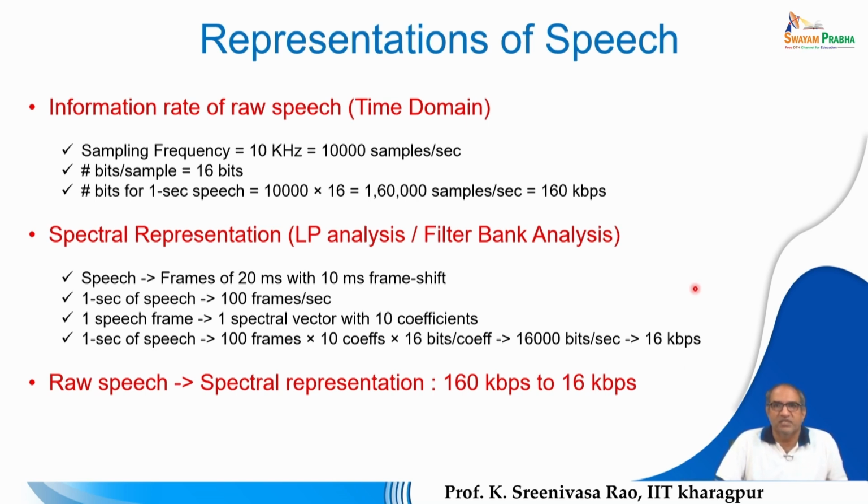That quantization can be viewed as scalar quantization. That means we have some value and we quantize it to the nearest known level or approximate value. In that process, since we are approximating instead of representing the actual value, there will be some error, and that error is known as quantization error. It is scalar quantization: since the value is real and cannot be represented with finite precision exactly, we represent it using some finite number of available levels. We are just rounding off one value to the nearest value, so it is scalar quantization.